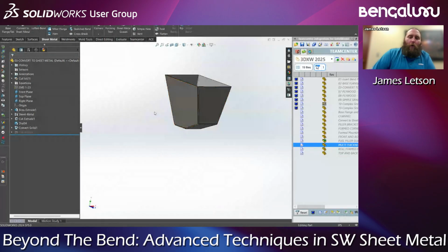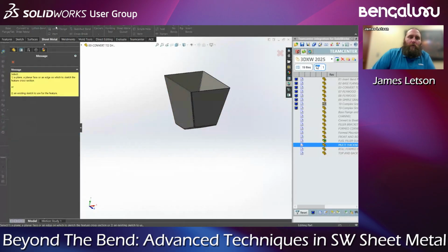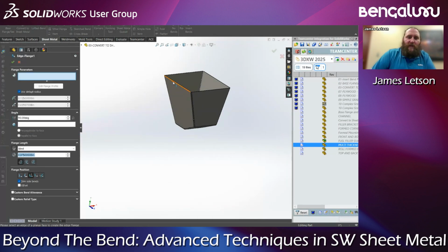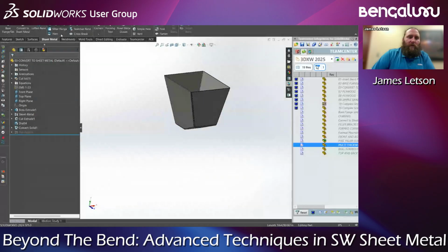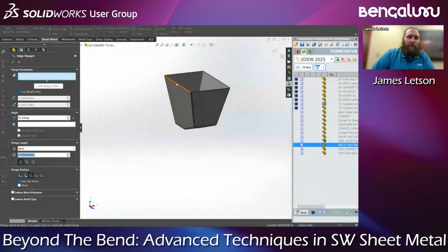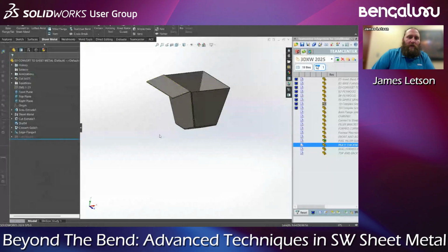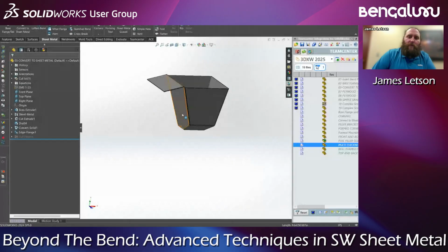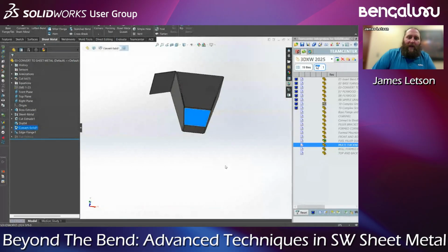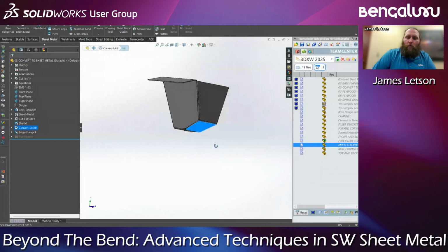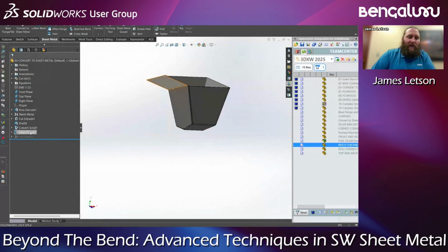And this sheet metal part can now have things like edge flange applied to it, right? So I can choose edge flange, and I can drag an edge flange off of there. Well, if I wouldn't hit escape too many times, I drag an edge flange, and I can make edge flanges off of it. I could add a little cut down here if I wanted, or maybe I want this to actually be a multi-body part, right?